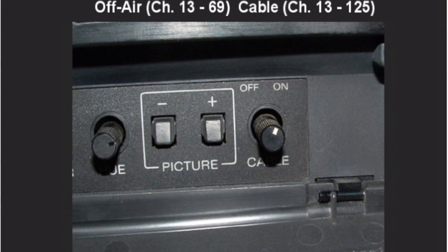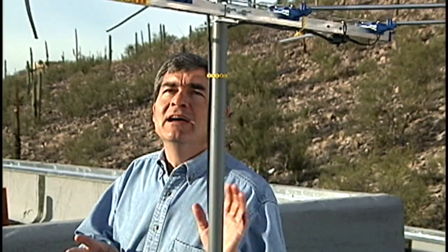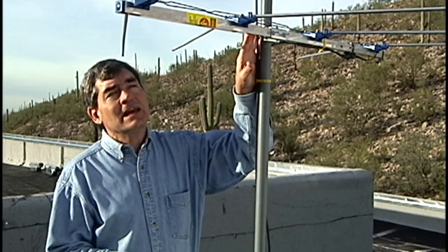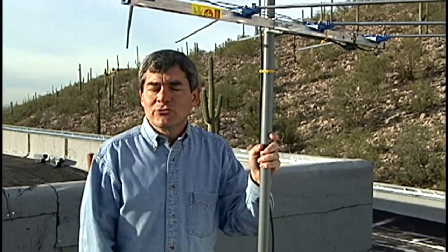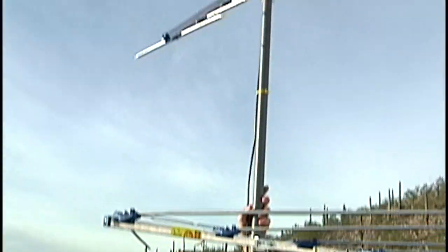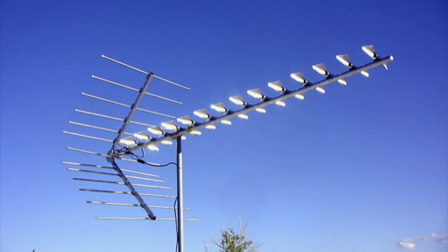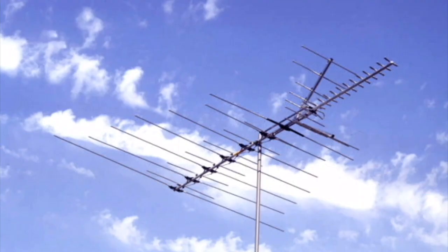Since off-air and cable channels above channel 13 use different frequencies, television or other receivers have to have tuning modes that select between cable or off-air frequencies. RF broadcast signals need to be captured by an antenna designed for the range of frequencies in the VHF or UHF band that the customer is interested in receiving. Now, if you only need to incorporate digital television signals, then you only need to select a good quality UHF antenna. Most antennas are designed to receive either the VHF band, the UHF band, or a combination of VHF and UHF band.